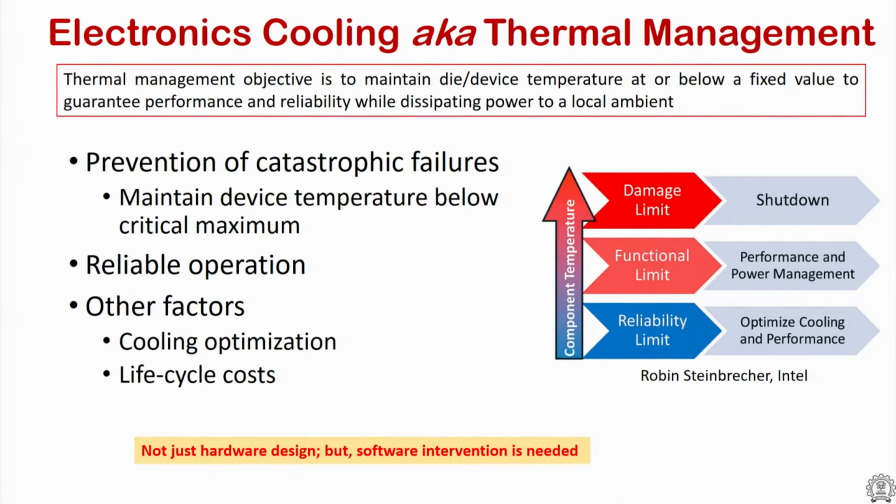As the temperature rises, the power increases and the leakage loss increases. As the leakage loss increases, temperature increases again. So if you don't provide sufficient thermal control and management, that turns out to be a positive runaway loop, and you can even burn your laptop processor.